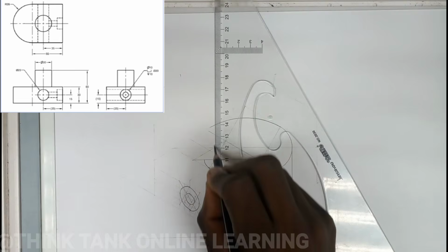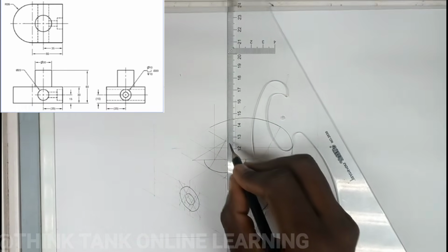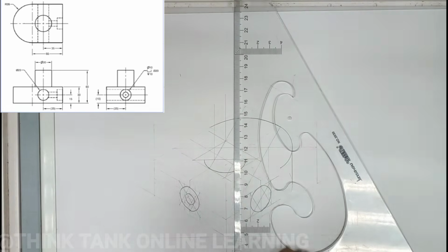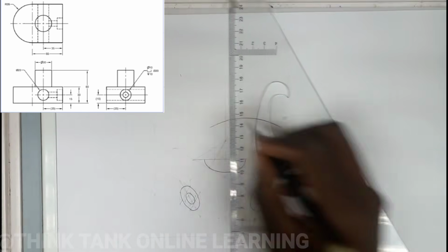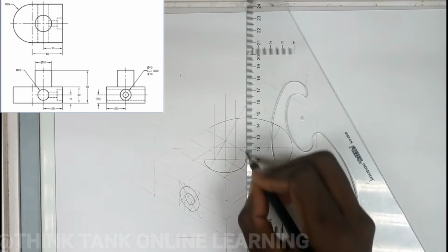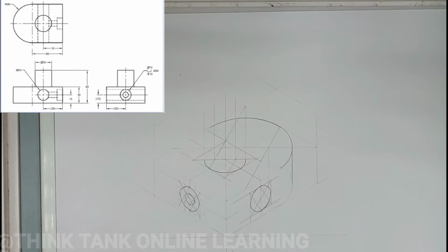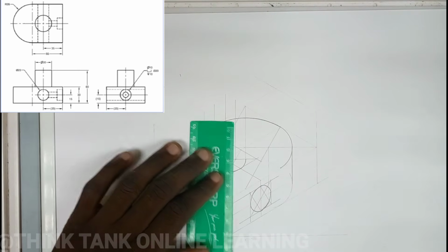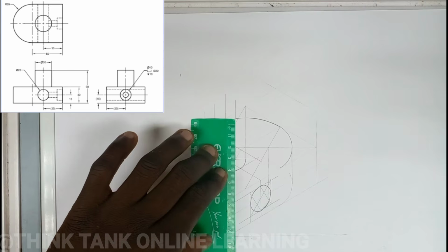So this was one of my center points. I projected upwards, and this. Okay, not forgetting this one and this one, which I didn't use because this part of the cylinder is going to be shown. Okay, then the edges if you want. Then from each and every center point you have projected upwards, you measure the height of the cylinder.